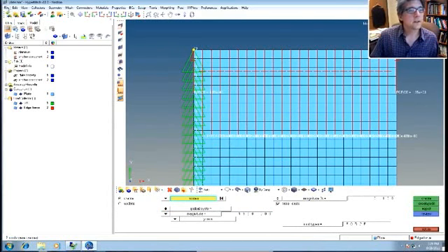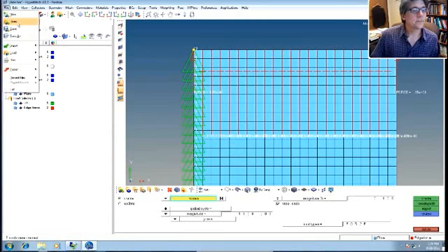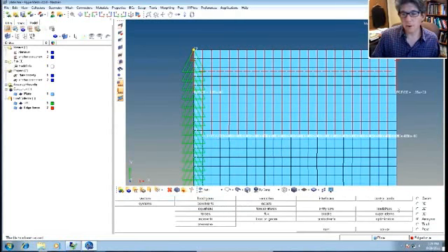So that's good. We've defined our loads and SPCs. And if you had multiple ones, if you wanted other SPCs for another load case, you'd have to make another load collector for like SPC2 or some other condition like that, and then create those, okay? All right.